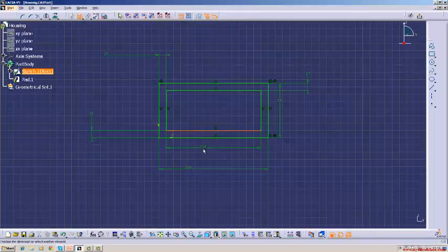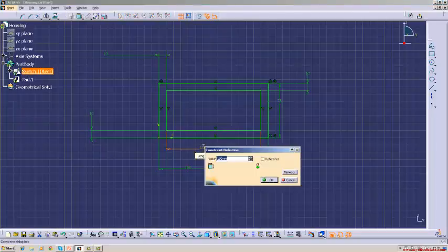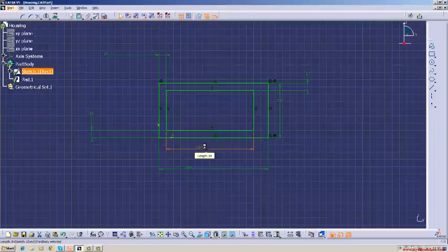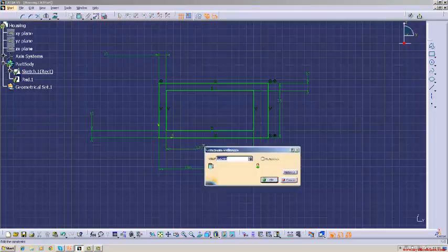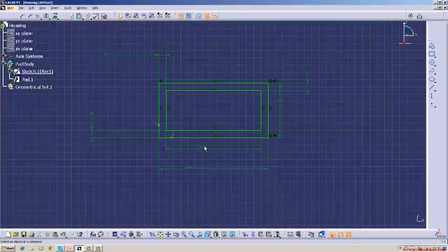This you can give value. 130. Now you can, these two distances are not constrained. Once you change this and this, automatically it will be set. Suppose I make it 120, see, it has changed. Okay? 120. So once you constrain, meaning once your dimension is set completely, if you add one more dimension, it should not be repetitive. That means you assign a dimension to the other things.